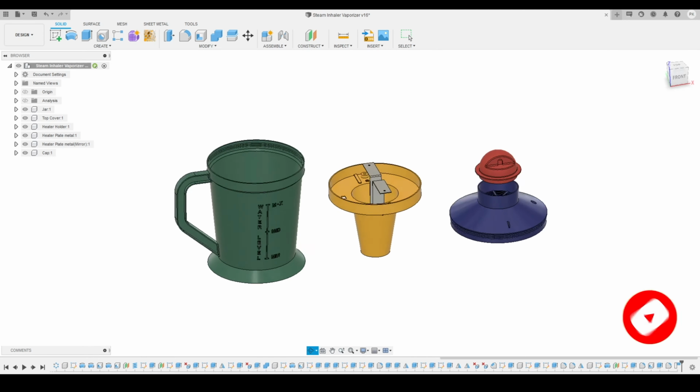Now I will define the dimension using the dimension tool. So this one is 50 millimeters. Here you can see I had just defined 50, and this one is 10 millimeters. You can see this sketch is not looking as good as our reference image, but still this is the right measurement because I had the product with me and I am measuring and reverse engineering this complete product. This alignment is also just 2 millimeters.